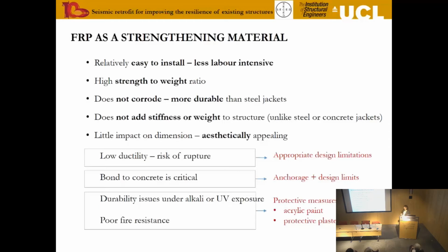The bond to the concrete is actually critical, so the concrete surface has to be prepared, angles have to be smoothed, and some care has to be taken to make sure that bond actually happens, and indeed additional anchorage is often necessary through mechanical devices. There are durability issues in the case that it's exposed to UV light, etc., but again, appropriate care or protective covers can be put on, and poor fire resistance, which again is a concern, but again, you can have intumescent covers or different types of interventions, etc.